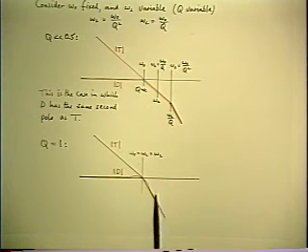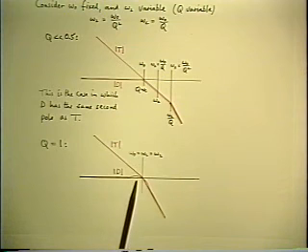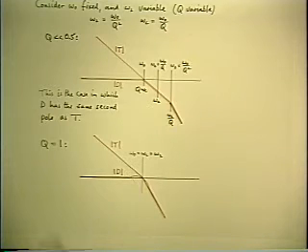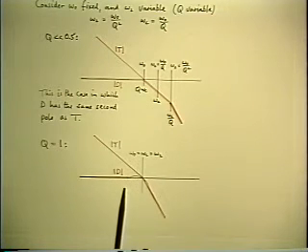Now remember what D is telling us. This is the shape of your closed loop response relative to the specification. So it means your closed loop response is beginning to build up a little bit into a peak. And you've got to keep that within the tolerance of your specification.